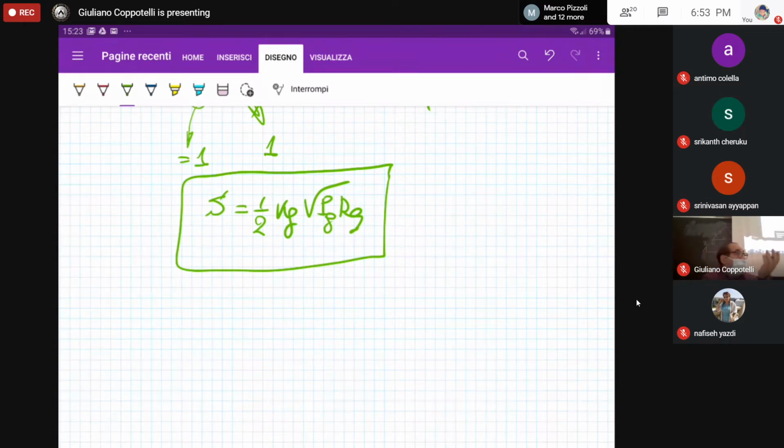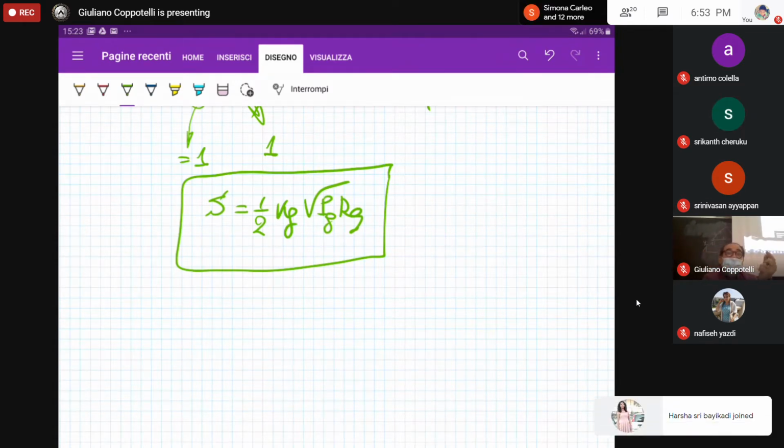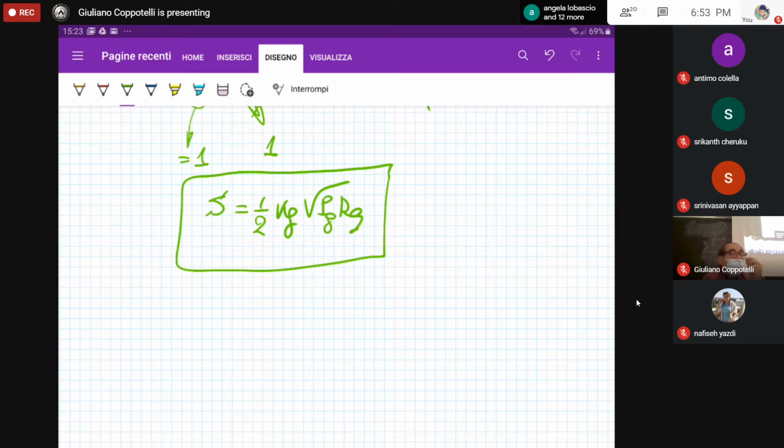That is because if we are putting the compensating strain gauge in leg number 2, we are setting also the circuit efficiency to 50%. That's the reason why we have a reduced sensitivity.